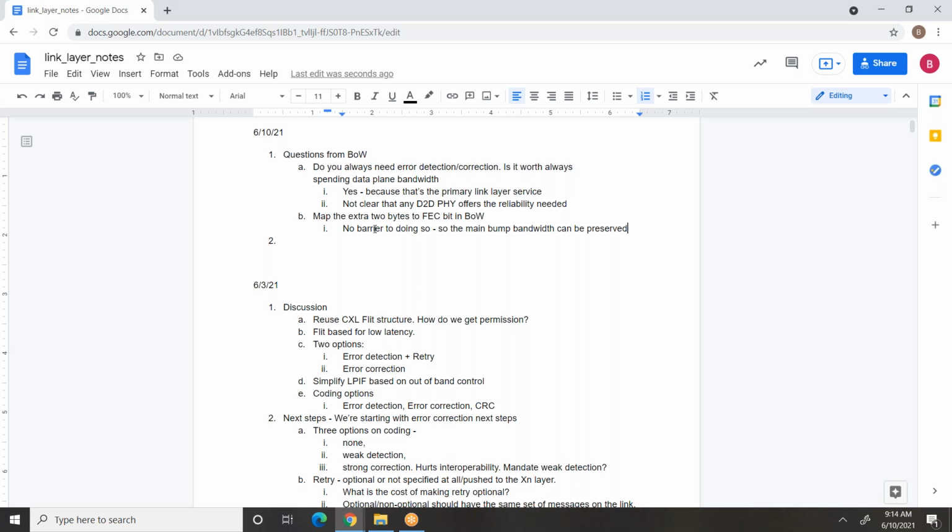I basically extend the flit to, say, 544 bits, for example, but my data width is still 512. The number of lanes I'm consuming is consuming 512 bits, and I do what's called a shift and merge. I basically just wrap around at the boundary and push the data down. I don't have these extra sideband bits. There's no extra sideband bits to find. You won't see that for an XSR or USR FI. So I guess the question is, in your case, if you turn off ECC, you can just use the entire 512-bit flit for data, basically. Okay. Yeah. Okay.